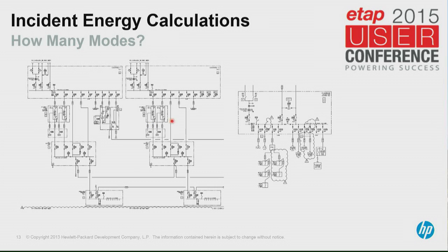So what you can see here is this is the UPS system serving the critical load. This right here, this side of the isolation breaker, this is the load bank loop. You can bypass the critical load, which is down here, either through this direction, or this is a bypass feed here as well, which allows you to use the same substation, this maintenance bypass substation, to either feed the load through its generator, bypassing any given generator, any UPS. We can basically reconfigure this data center and feed everything any which way but loose. Okay. A film reference which nobody in this room is probably going to get because it's way before their time.